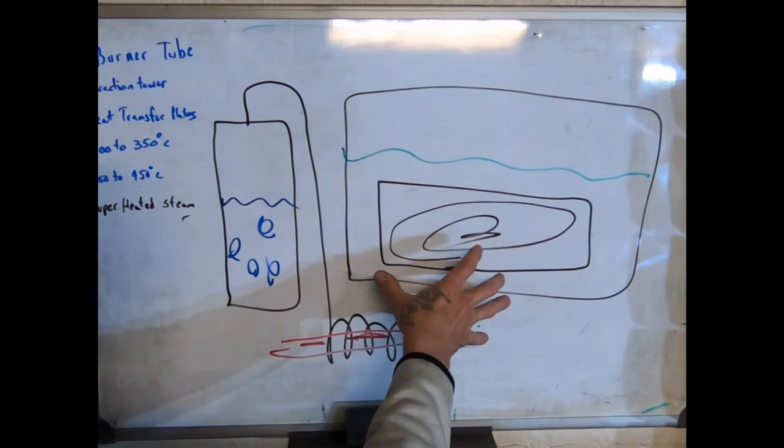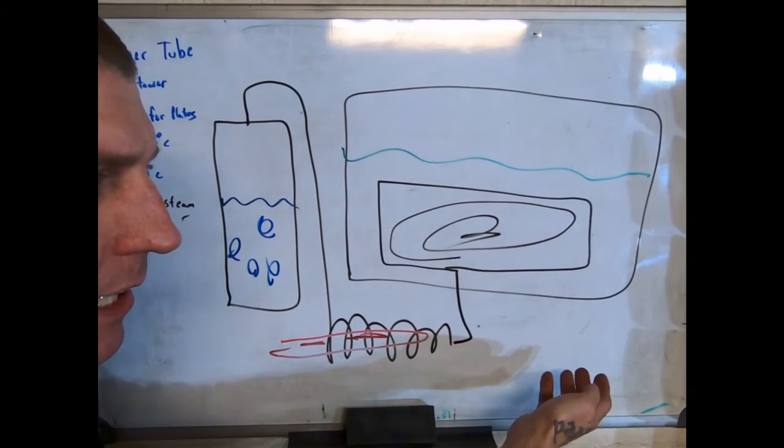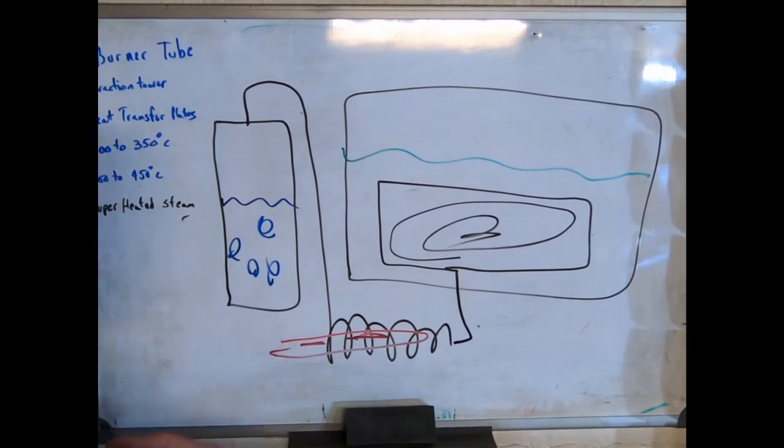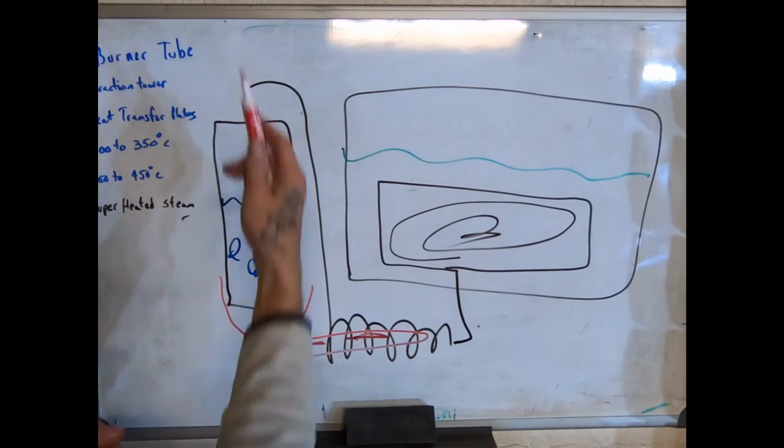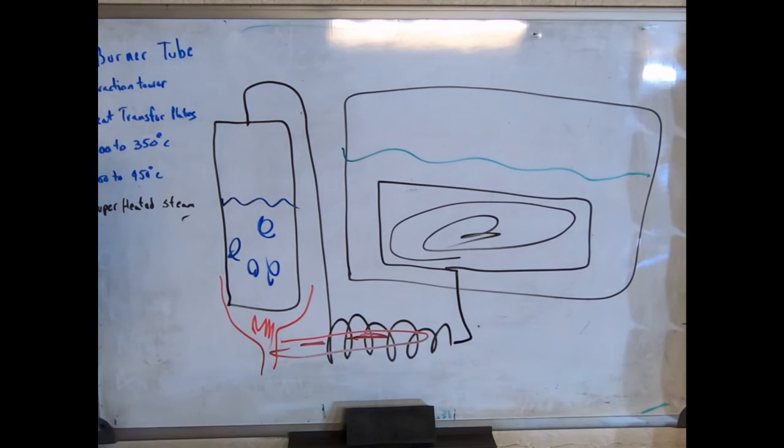Superheated steam gets us out of having to worry about damaging the thermal fluid. I know water's kind of hard to come by in the desert, but it's a lot cheaper than $1,000 a liter for 100 liters, whatever, of the thermal fluid. Oh, I forgot. We would have another burner down here, of course, getting the water boiling in the water boiler tank, and that would give us the steam, which we would then superheat with another burner that's heating this coil, or it could be those box things that I showed you.